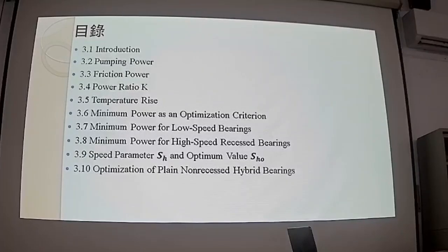So we have some assumptions for the calculation of temperature rise. We assume the overall friction power goes into the lubricant 100% without any radiation or convection to the air. Okay. So this is the worst case scenario. You can estimate the temperature rise for your lubricant.